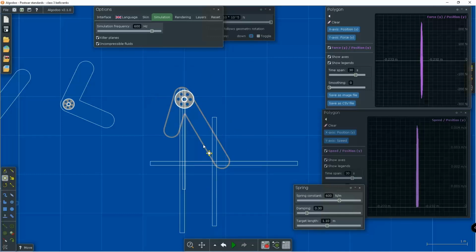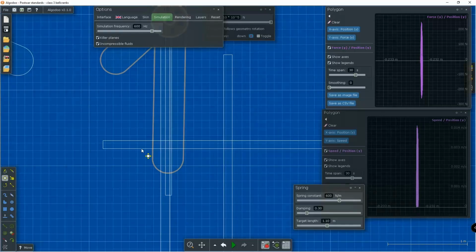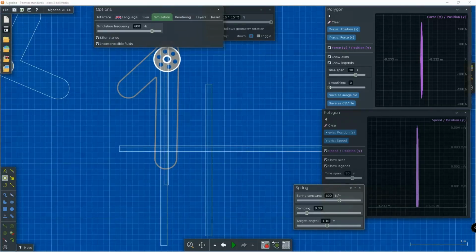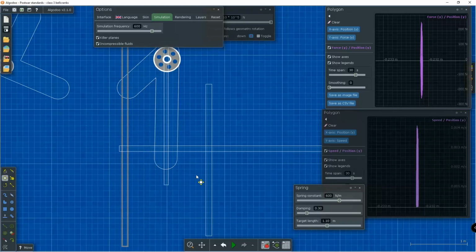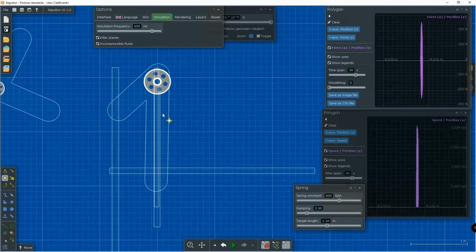But on the other hand, if we do have the load arm being parallel with the load force, as we know, this arm will still be able to apply a sideways torque to that output arm and eventually also impart an upwards component force. Anyways, regardless of the direction of the actual load force vector, this here would still be a class 1.5 lever.